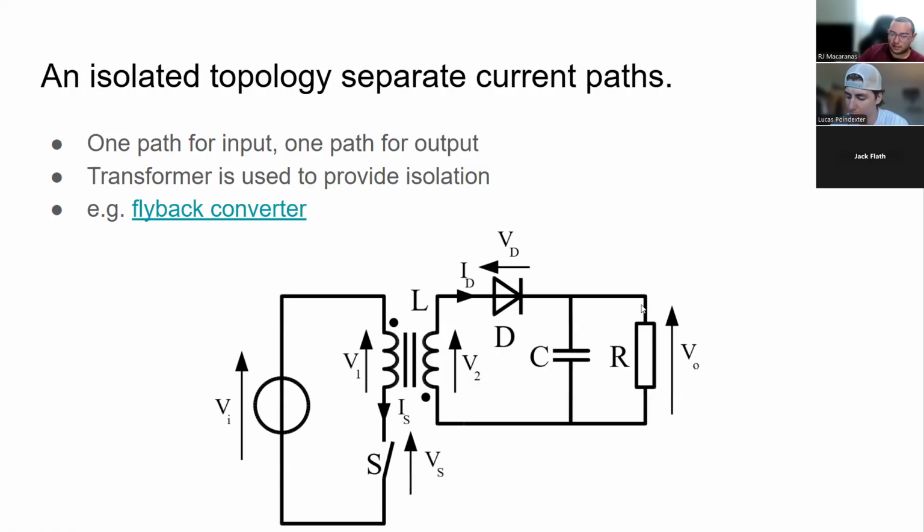In this case, where I have a transformer, if I short the load, it's going to try to take more current than this transformer can handle. The transformer will saturate and it might break, but at least it will protect the source voltage from breaking down or doing something worse. So transformers come up a lot in systems where we need to protect the input from the output.